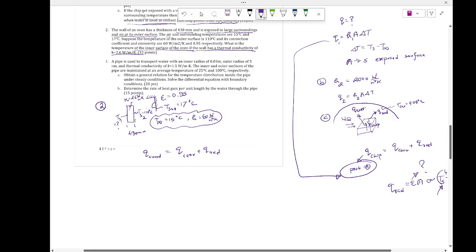Now, why did I say convection plus radiation? Because of the temperature. The surface temperature is way higher, 110 compared to 15 and 17, right? That's why I can claim that, otherwise not. Then there's another problem that I'm facing: I don't have the surface area. If you don't have a surface area, you'd like to do a flux. Very good. See, the double inverted comma denotes flux, right? It's good so far? You understand why I'm doing the flux, right?